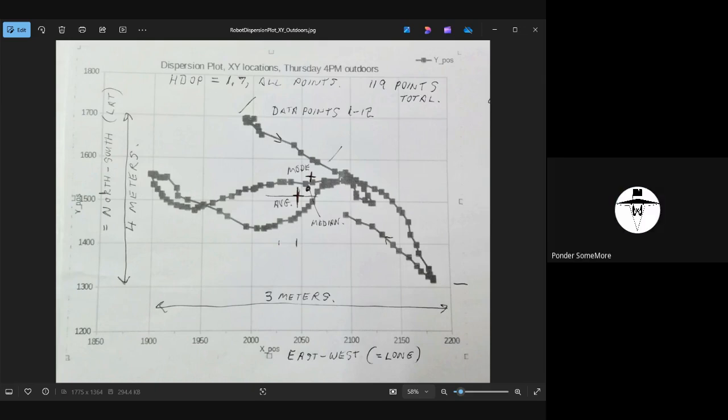Sure. You can use the exact same type of receiver for both the rover and the base station, and it gives you some failover redundancy, especially if you end up getting another base station that's in the area. Then you might have a second one for your robot or a spare when your antenna dies. So it's common to use two F9Ps for that kind of situation. And if you do happen to have a correction source, then you can wait on the base station, and you can get started with just the one for the robot.